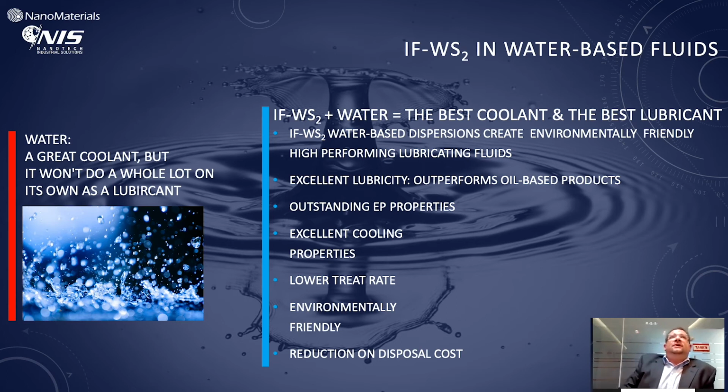The combination of tungsten disulfide inorganic fullerene-like particles within water proved to be a high-performing lubricant fluid with extreme cooling properties and outstanding extreme pressure properties. It requires low treat rates, it's environment-friendly, and as a result, since it's oilless, it saves on disposal of used liquids.